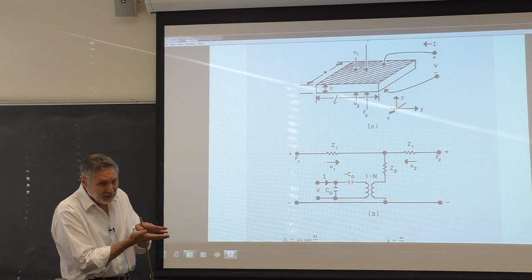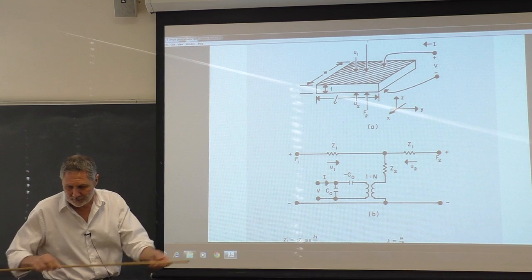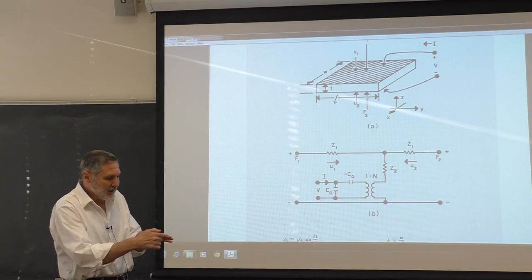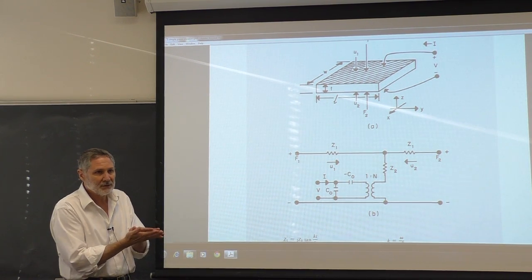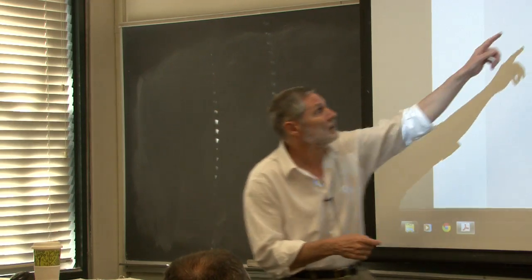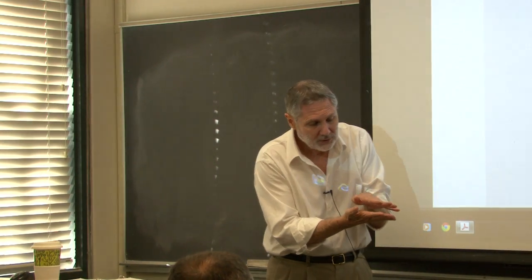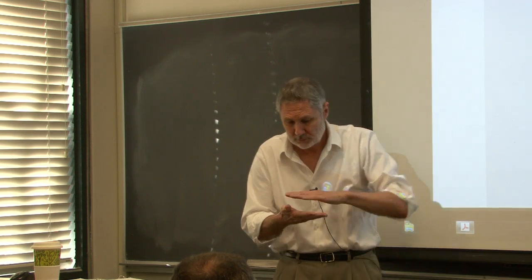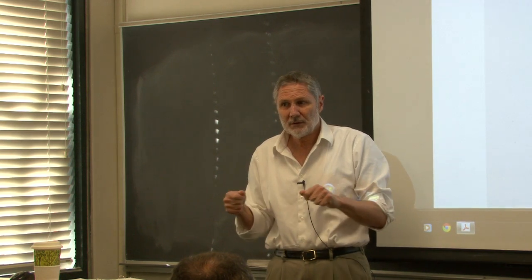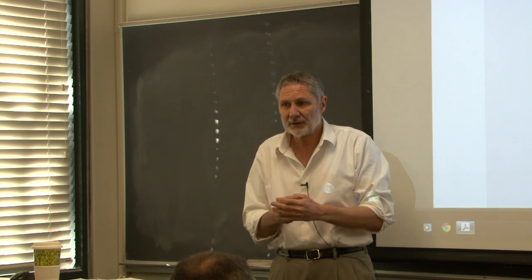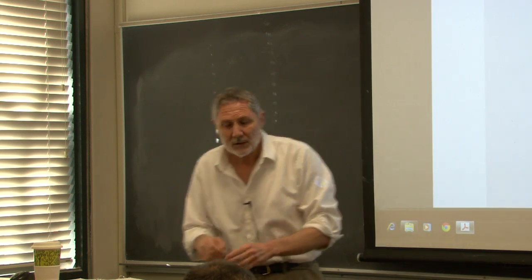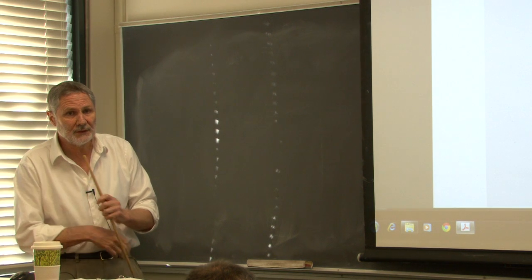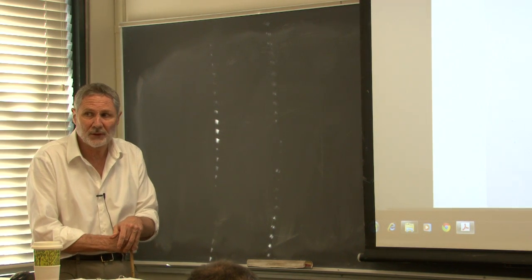So we got this plate here. It's vibrating longitudinally like this, and it's essentially infinite in this direction. So the wavelength has to be small compared to these dimensions. What's going on here? Is it bulging? No, this is unilateral compression and expansion. So that's different. And that's going to force us to solve this problem in a different way.